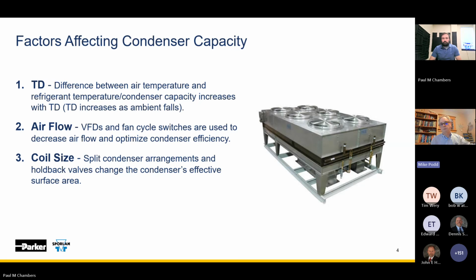But then next, we need to do some additional refrigerant side controls to help keep the liquid pressure entering the expansion valve up close to the operating window.